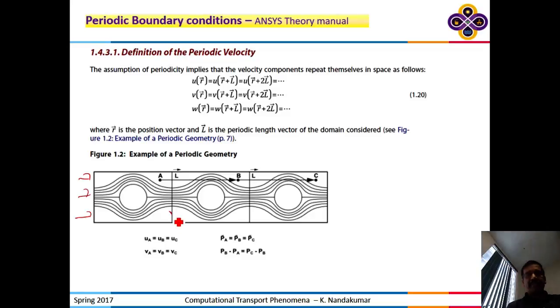For example, if I take this block, I can translate that by 1 unit to the center here, and I have the same block. So if I know the velocity here, I know the velocity there. Why do I have to solve for the entire length? Why would that argument make sense? Because if you solve it over the entire 3 cylinders, you need much more grid points. You are going to solve a problem that is 3 times as large as compared to 1 unit cell, if you can extract that unit cell.